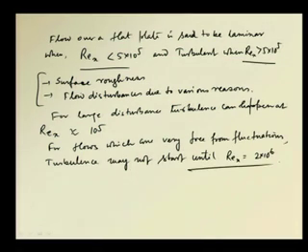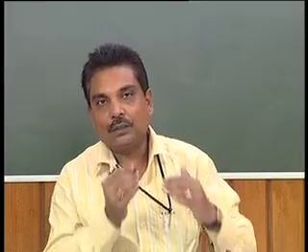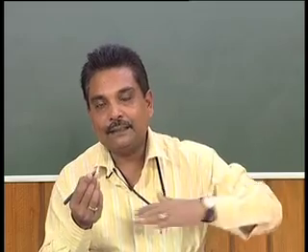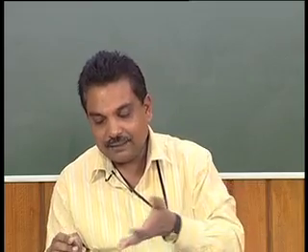So, this is one interesting point. When you have a very smooth flow, with little disturbance, and the plate wall is less rough, then we can have the transition even at later stages of the length of the plate. So, this boundary layer profile can be dependent on the surface roughness and flow disturbances due to various other reasons.